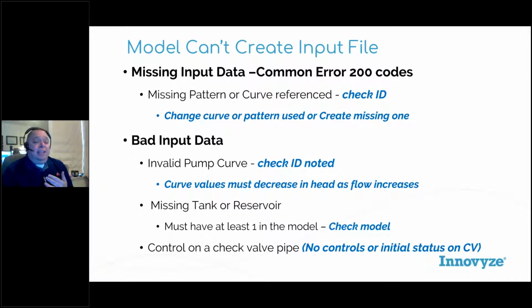Another common thing is if I referred to either a pattern or a curve that I forgot to create. Not often this happens, but it definitely comes up. It will tell you, hey, I don't know how to solve that because you're asking me to do something that doesn't exist. It'll tell you the ID of that, so either create it or change it to something that does exist if it was one that you got rid of.